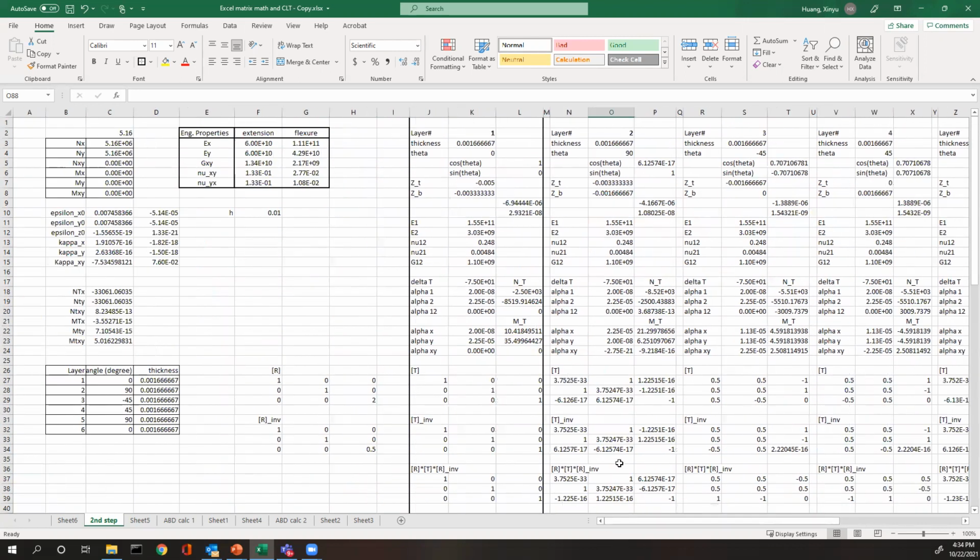So I have this thermal stress part programmed in. I can point you to the blocks where I have this calculated. It starts from here. So I first assign each layer a delta T. In this case, it's minus 75 Kelvin. I assume the stress-free temperature is somewhere high, and room temperature is 75 degrees below the stress-free temperature.